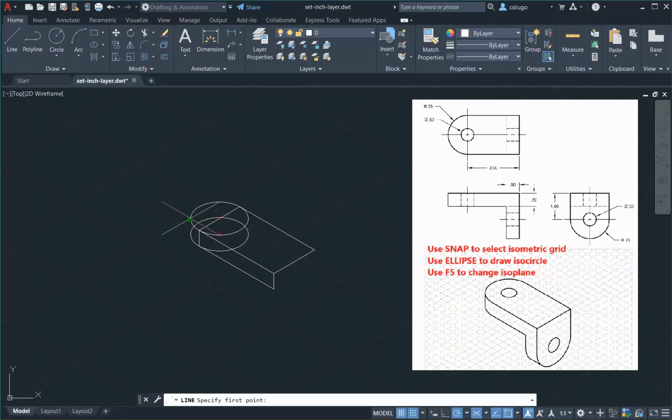You will see it's hard to find a tangent because we use the grid on, so it's snapped to the grid. You deselect this one, and it will allow your mouse to move to the tangent point. So we use this point here, then you go down to the next point at the bottom, and then you finish the connection of these two. Alright, that pretty much finishes the left-hand side, the top face, but we need to trim this a little bit.